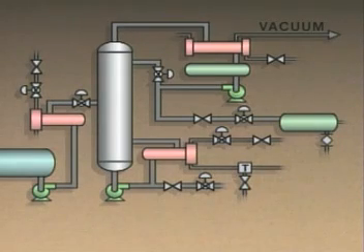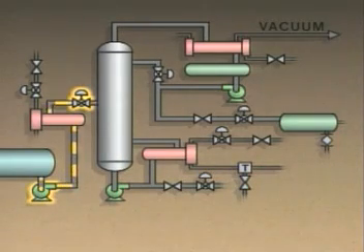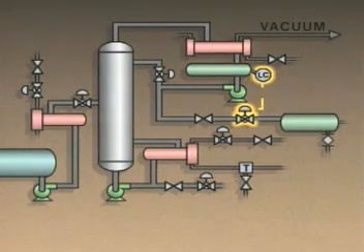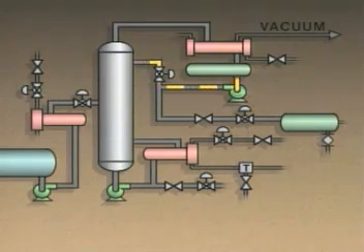In this system, the first steps in the short-term shutdown involve stopping the flow of feed mixture to the column. First, the steam flow to the preheater is shut off to stop the supply of heat for the feed mixture. Then the feed pump is shut off, and the feed control valve is closed to stop the flow of feed to the column. When the level drops past a specified point, a level controller on the receiver automatically closes the overhead product takeoff valve. This stops overhead product from being drawn off and places the system on total reflux.